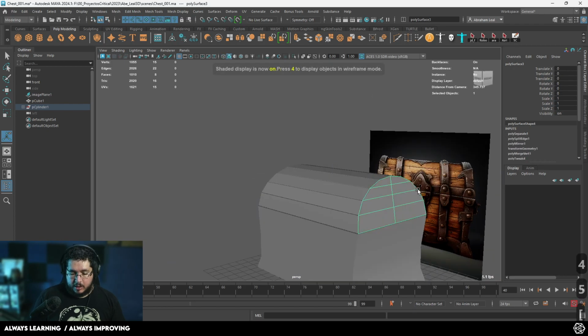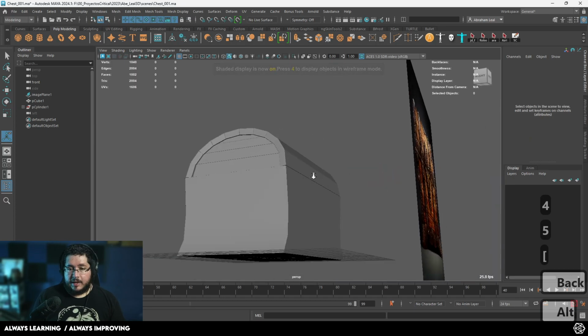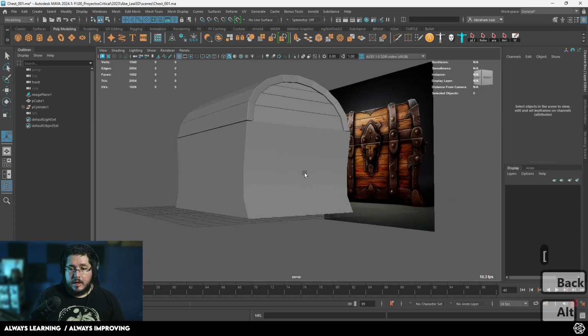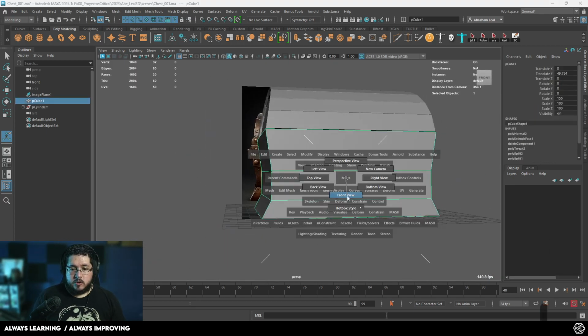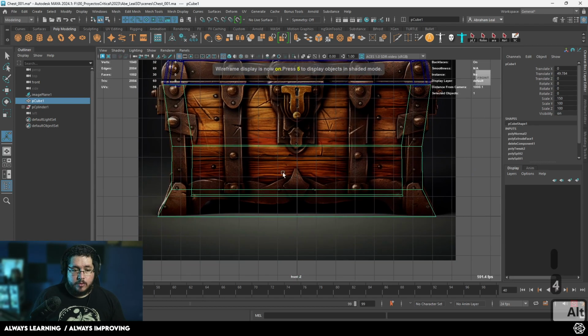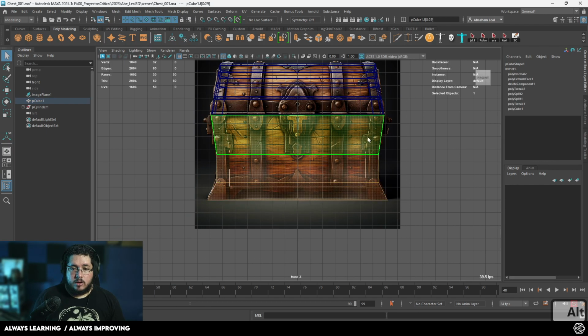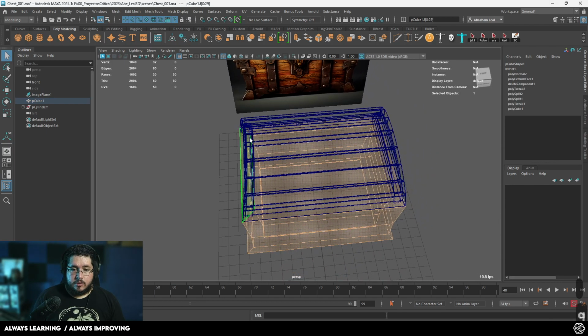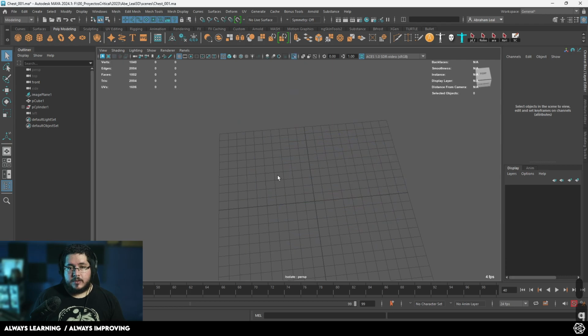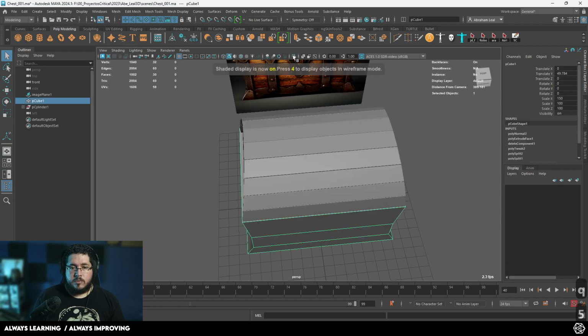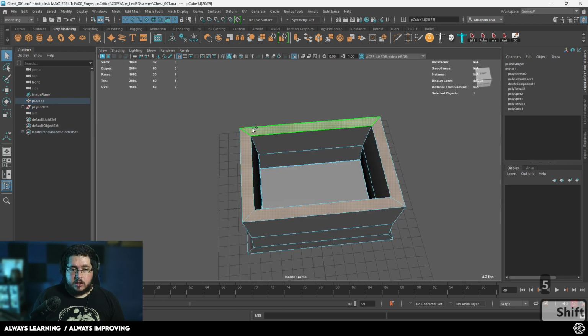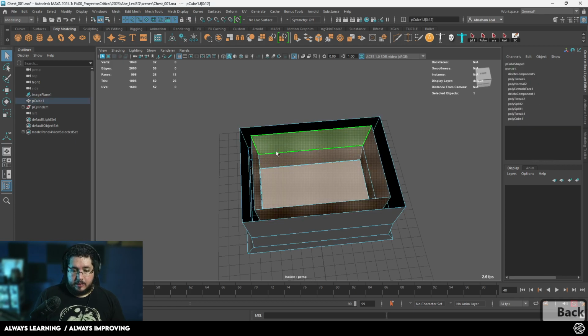So you can see it's going to be over here. We can delete this one now. We're going to have this very nice effect right there. Let's do the exact same thing with the elements right here. If we go to the front view, one of the things that I'm going to do here is, again, delete the inner side or the inner sections of these things. Here's a quick way to remove thickness from an object. Grab the object, grab the edge loop that gives it the thickness, and then delete all of the interfaces.